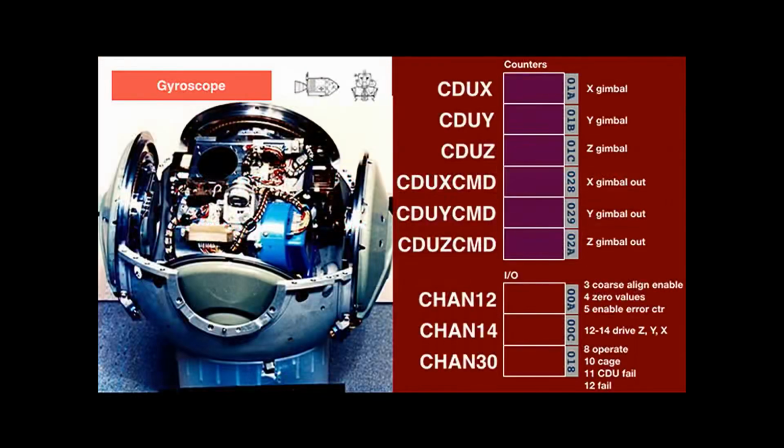The gyroscope is the core peripheral that the Apollo guidance computer was originally built around. The Apollo guidance computer rotates it into a certain base position with the CDU command counters, and then the gyro detects rotation around the 3 axes of the spacecraft that can be read from the CDU counters. Using the gyroscope, the spacecraft always knows its attitude, that is, its orientation in space.